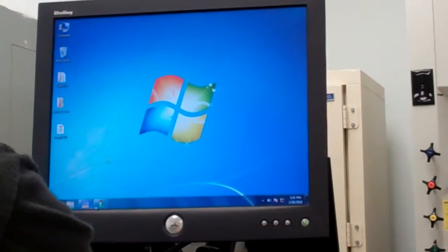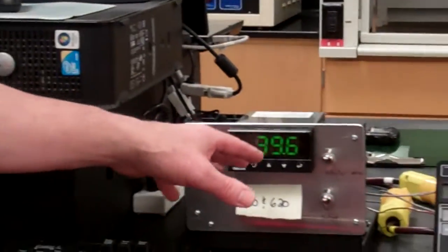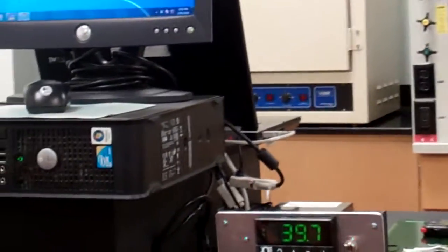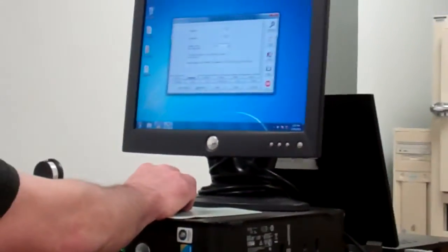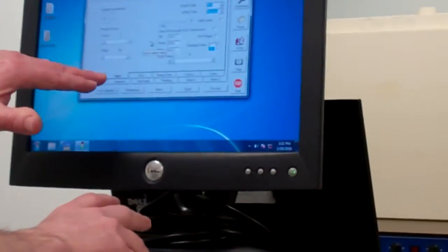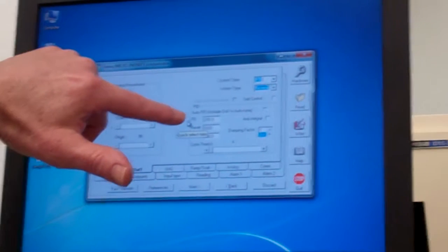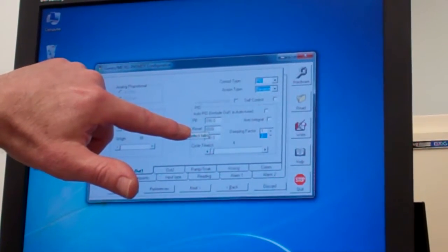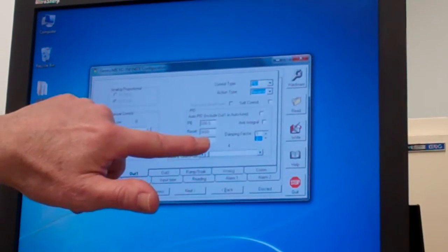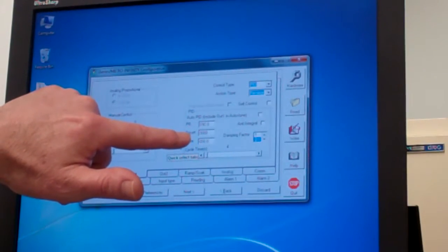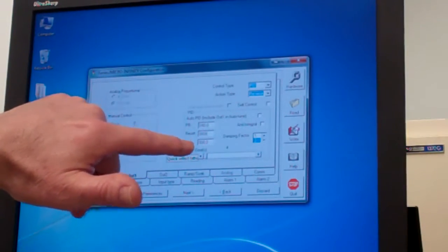experiment instructions. Now with respect to the controller configuration program of the file, again, when you come in, the system will be at some steady state. And for this one, what we have to do is go to the output 1, and here's where your proportional band, then this uses proportional band instead of gain. And then you have reset, and then you have rate. So this rate is the derivative setting, which will keep to 0 the whole time. The reset is the integral setting, which you will change in part of the experiment.